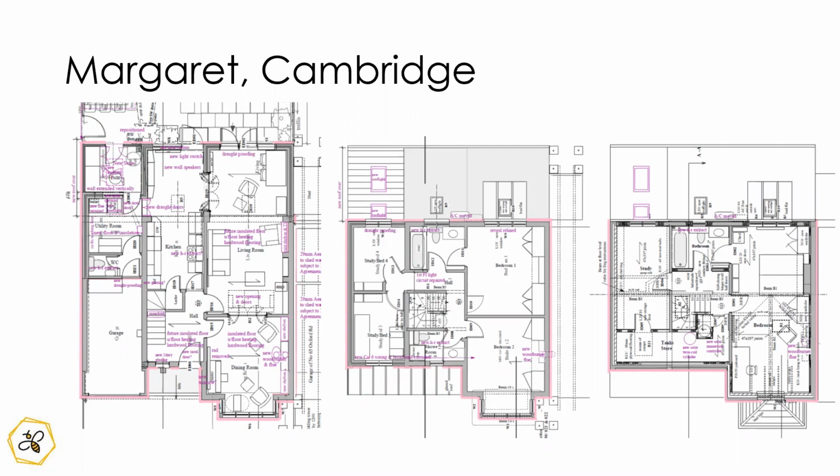Yes, well, 210 is enough for us. I don't know why we would be wanting a bigger tank. He seems to be suggesting another 100, which I don't see the point of. They're separate circuits, so it has no effect on the heat pump, does it? It may be because it's a solar cylinder, and obviously a heat pump generally works at lower temperatures. So you need to use more of the hot water stored to get your comfort temperature in when you're washing. You're not blending so much cold with it. So they tend to put more capacity in to accommodate that.